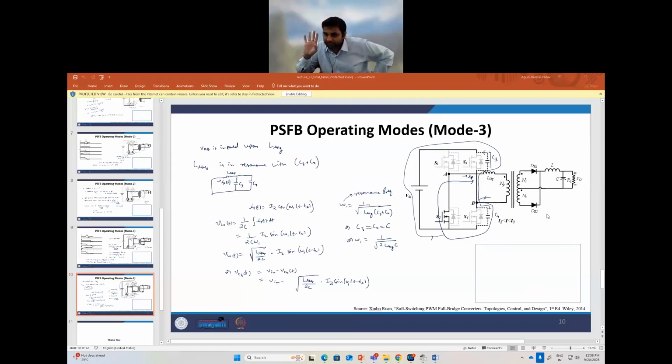And I also suggest don't go by the numbers you get in the simulation. Put it in the hardware and see. Why? Because if you are doing MATLAB modeling, you are doing behavioral modeling, you are not considering any circuit parasitics. But that zero crossing is primarily because of the output capacitance of the devices, because it takes some time for the devices to change state.